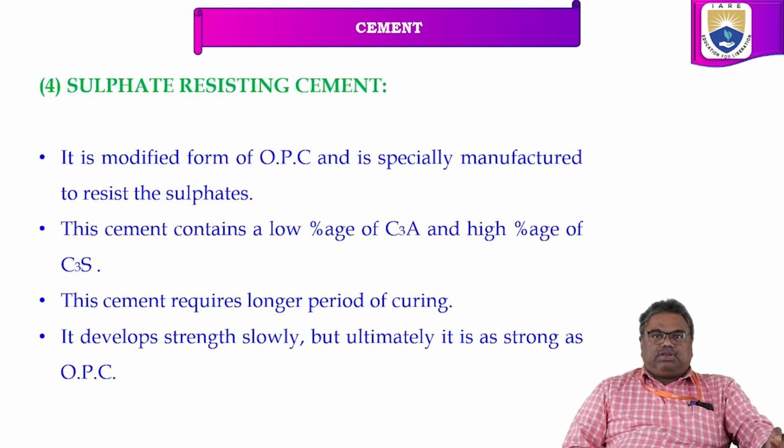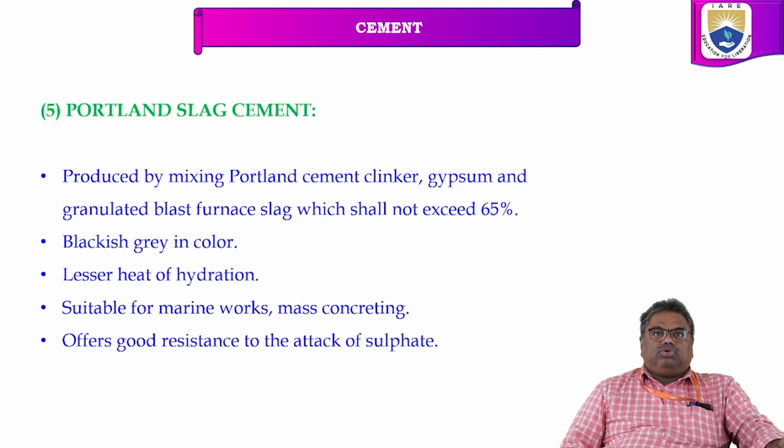This cement requires a longer period of curing. It develops strength very slowly, but ultimately it is as strong as ordinary Portland cement. Especially, this sulfate resisting cement is used for sulfate resisting structures. So this is about sulfate resisting cement.